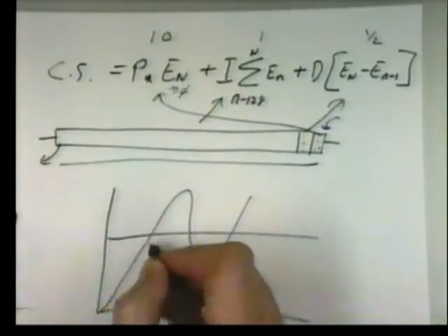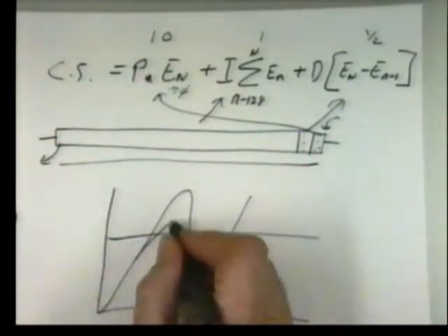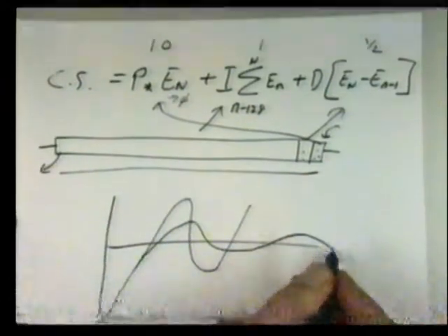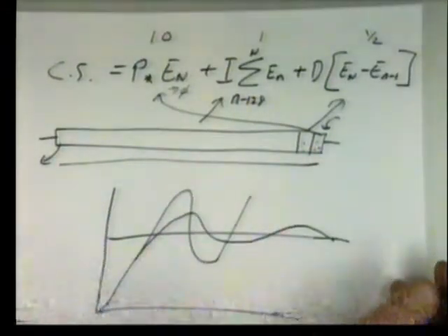And what will happen with the derivative? The integrator will do that. The derivative will tend to slow us down a bit and smear us out. It will slow the response down. It is a damping term, but it does stop the integral runaway. So there we have on-off control and three-term control, PID control. These are the key algorithms that you need to study, that you need to know about.